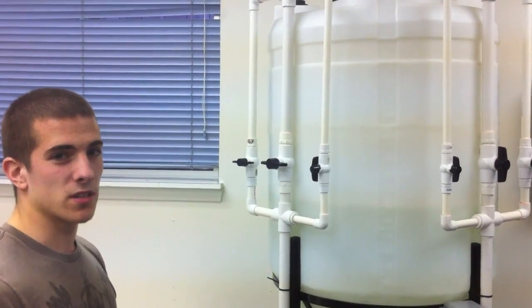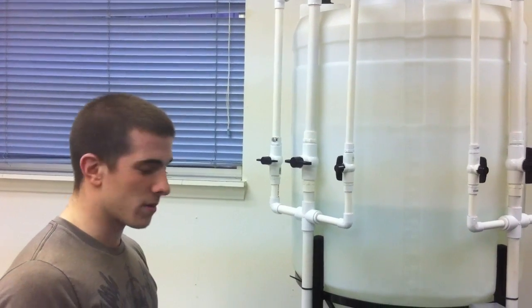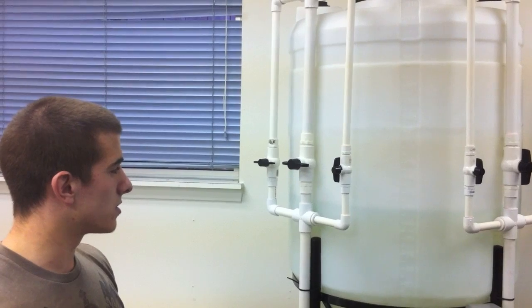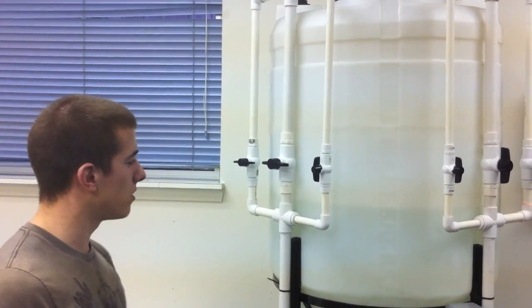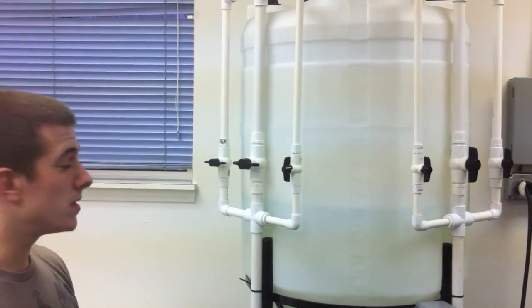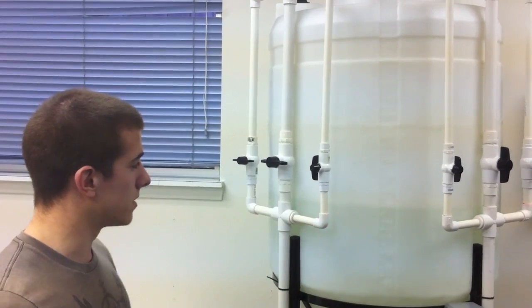Currently we have them limited to 75% duty, so as not to damage the pumps, we just want them running at a maximum of 75% of their full 60 hertz. So that would be 45 hertz, which is what it's currently running at to keep up with this set point going through such a small pipe. As you can see, it's pretty steady. Our P, I and D values are pretty accurate to hold the set point right at 50 like we wanted.